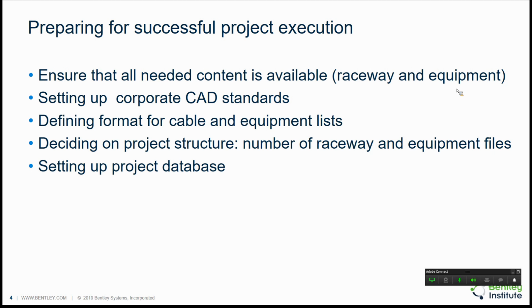You will have to define the format of the cable and equipment list that you plan to use. And you need to decide on the project structure, which means how many raceway and equipment files you want to have, how many users will be participating in the project, and so on. And finally, setting up the project database for your new project.